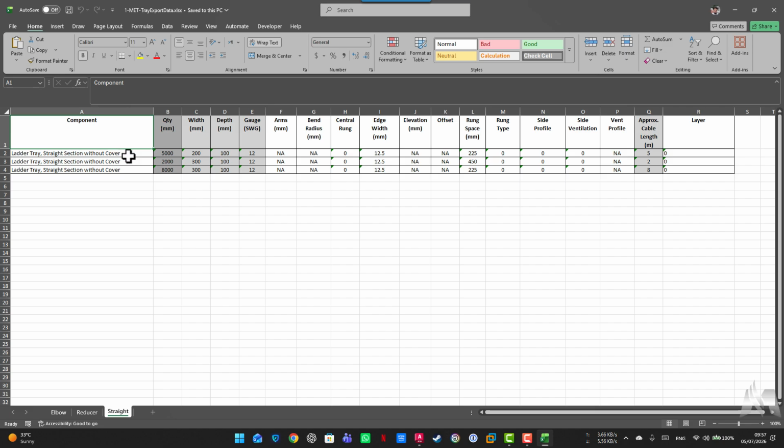Okay, this one is the 5000 mm, 200 width cable tray, and these two are the 300, but they have only one thing different, which is the RS value, the run spacing value. So in the BOQ, it has also made the change and bifurcated them. And now this Excel sheet is something that you can work with and prepare your BOQ. You can apply the costing over here.